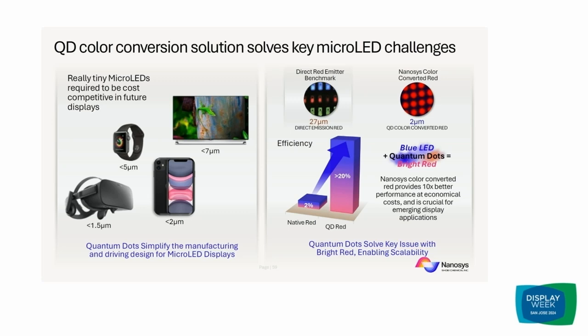And with patterning, red quantum dots can be put directly onto the blue LEDs and achieve efficiencies 10 times better than just the comparative red micro-LED. So going from red micro-LED trying to use direct emission from a solid state emitter to a quantum dot down-converted red on a blue micro-LED, the increase in efficiency is an order of magnitude in that case.